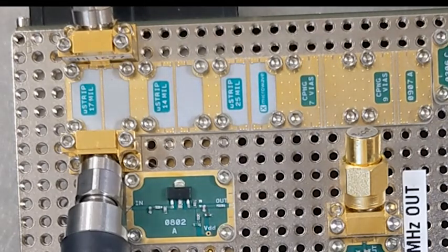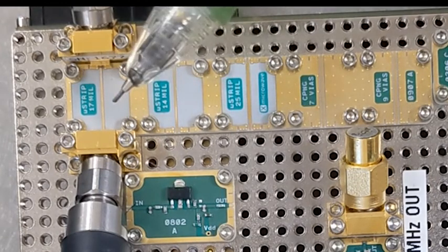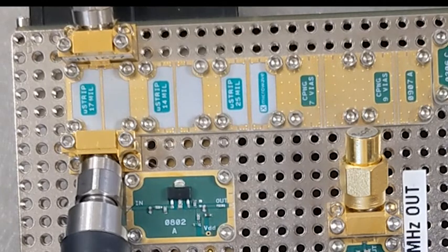The change of the width of the transmission line will really affect the characteristic impedance Z naught of the lines. If the Z naught changes, it will lead to impedance mismatching to your port impedance. That will change the performance of your result, basically changing the magnitude, the insertion loss, and the return loss. So that is mainly the difference. This time we're just going to pick the 17 mils to do the measurement and see how it works.